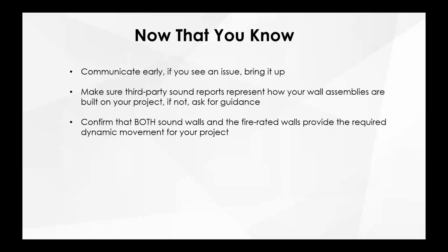Confirm that both sound walls and fire-rated walls provide the required dynamic movement. Okay, I just talked about how there's no requirement for sound walls to have any kind of dynamic test. There is for fire, but not for sound. So you might want to ask that question. It's a little bit easier if you're going towards the fire side because you already know that provides the dynamic movement. But again, if it's just sound, bring up that question. Hey, this is a sound wall. Structural engineer said it's going to move 1/4 inch up and down. You're requiring a 1/2 inch joint with sound sealant. Where am I going to get that movement? So bring that up.